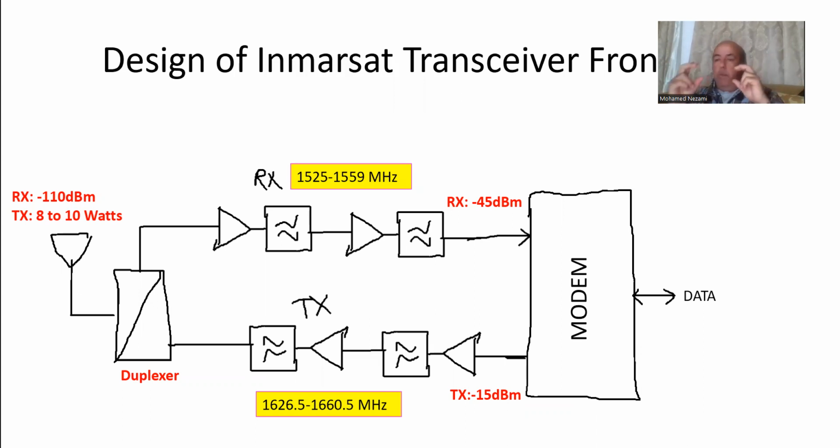But it doesn't mean that when you have two pieces, let's say an amplifier and a filter, each one 50 ohm input and output, with return loss better than, say, 10 dB, it's always as simple as just putting them together. When you come to the schematics, you have to tune, you have to optimize, you have to add little inner stage tuning pieces. So you end up with more to it than what I'm just going to show you here. But this is a critical part of that design.